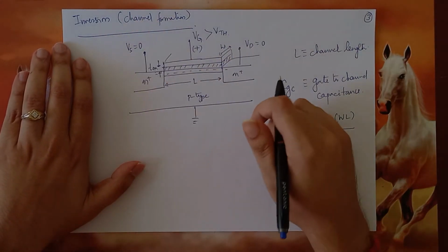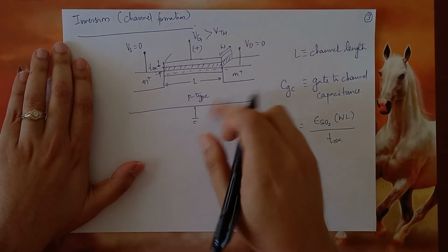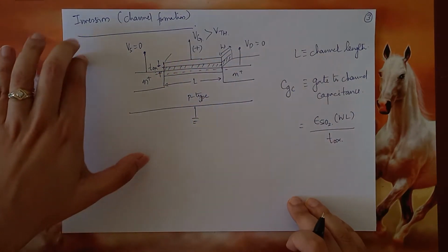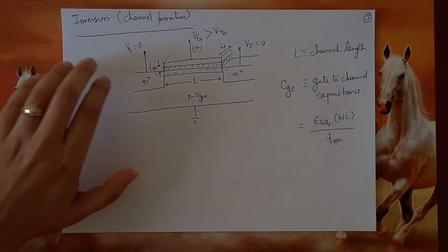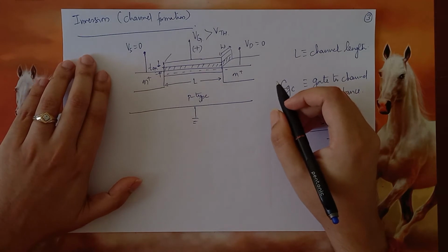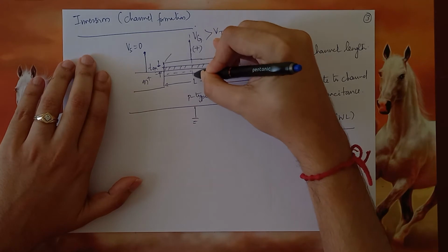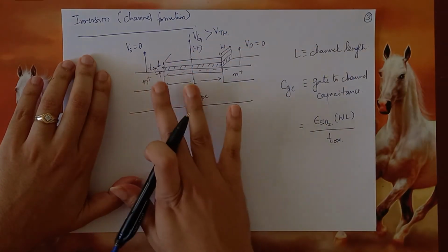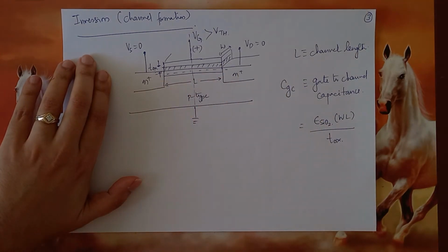But before we see that, let us try to model this capacitance in a slightly different way. We have essentially modeled this capacitance as a big single one that exists below the metallic layer. Rather than doing this, we will draw a line of symmetry over here, and the left half we will call with respect to the source, and the right half we will call with respect to the drain.